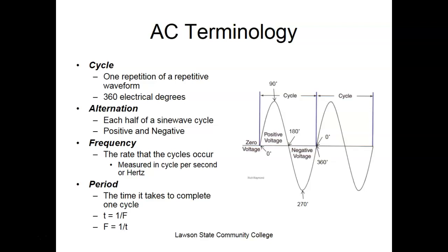Of course, we all know relays, right? We talked about relays. This one actually outputs to a relay contact. So what does that mean? We can set it up to control DC or AC in different voltages. We'll talk about the different ways we can control. This one right here is DC, the input, where we bring information into it, is DC, and the information we get out of it is DC.